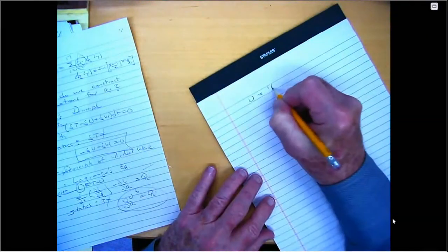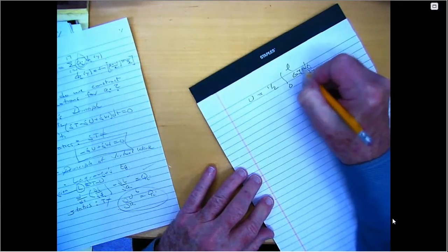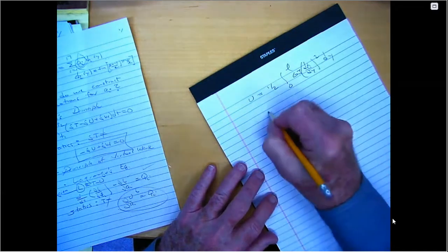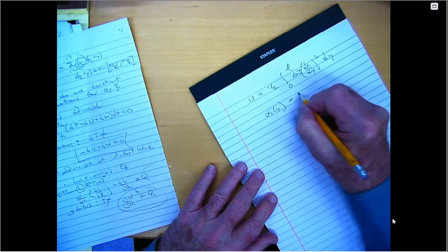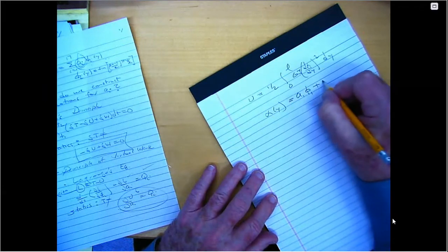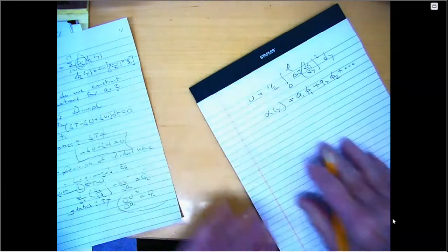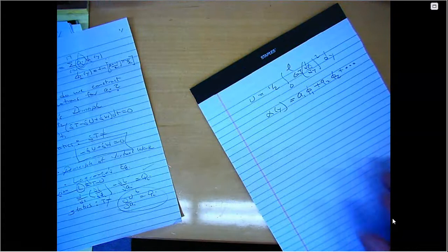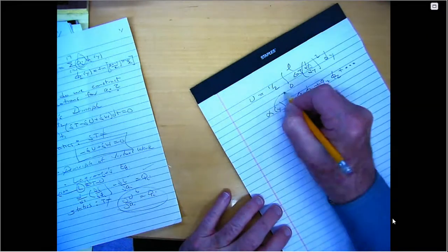U is 1/2 the integral from 0 to L of Gj d alpha dy squared dy. And I'm going to write out y now in longhand for two modes. It's A1 times phi1 plus A2 times phi2 plus other things. Now, if I were really doing this and getting a high salary for doing that, I would write this in summation notation. But the first time you do it, you might want to write it out. So we'll put that in here, and we'll get what?